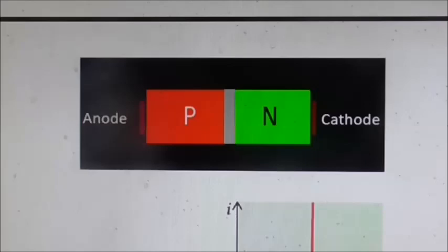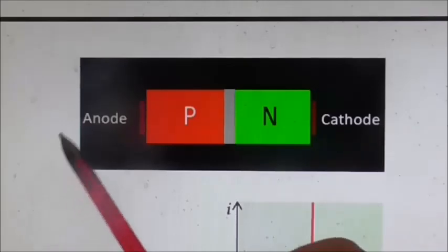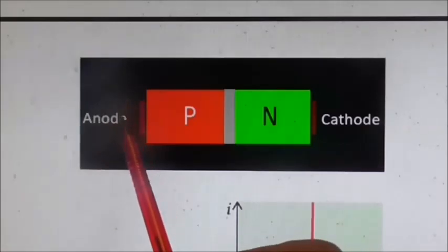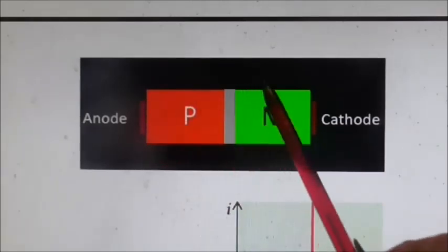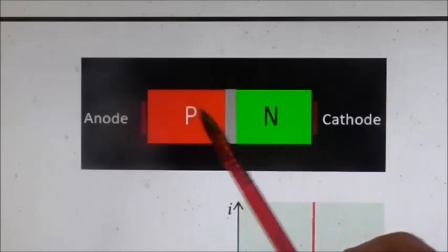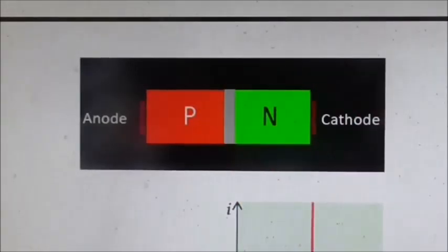Following on from that, we can do a forward bias. Now if we have a DC supply and we make the anode face the positive of the DC supply and the cathode face the negative of the DC supply, what will happen is this depletion layer will seem to shrink and vanish. And it's not really the layer itself that's growing and shrinking. What's happening is we're imparting energy. And so the electrons and the holes find it much easier to cross the gap between the P and N substrates and recombine. And the more we can do it, the more current we'll get.